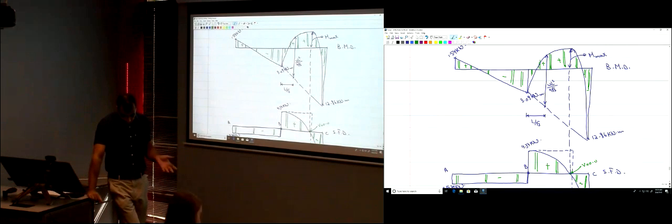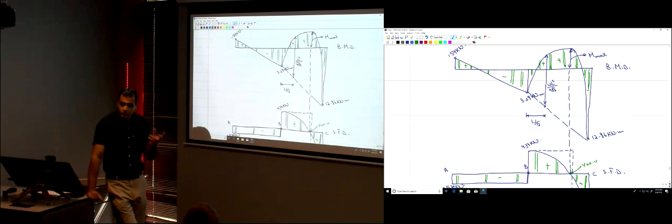And then, after writing the slope deflection equations, you need an equation of equilibrium or some equations of equilibrium to find the unknown kinematic degrees of freedom. And then once you find it from the equation of equilibrium, you substitute back into the slope deflection equation. You find the moments at the ends. You apply the equation of equilibrium to find the vertical forces if you need to draw the shear force diagram. And you can draw the shear force diagram and the bending moment diagram for your beam.